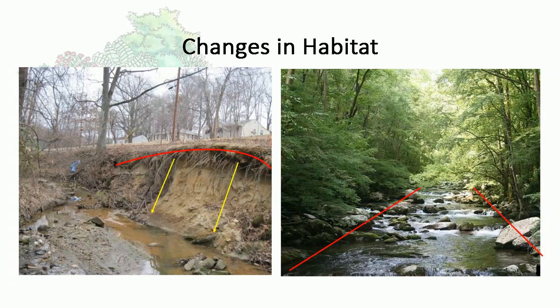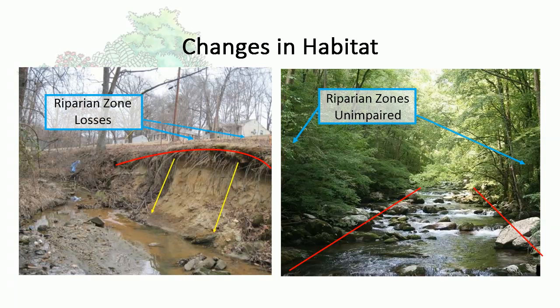Under the high peak flow conditions typical of urban streams during rain events, incision of the stream channel is incredibly common. Loss of the riparian zone, or floral cover near the banks, is another indicator of an impaired stream. Again, this is more common in urban streams and is due to a lowered groundwater table. Plant roots can become separated from the groundwater table and may not be able to take in water as effectively, hence little to no plant life next to the urban stream banks.